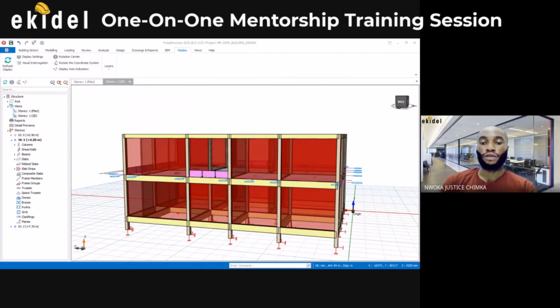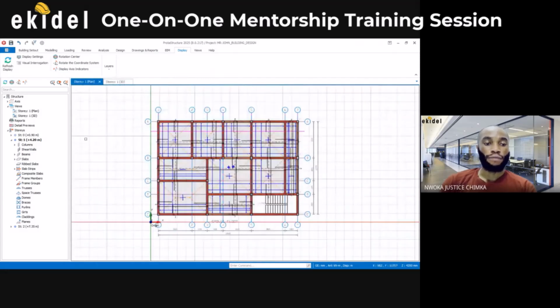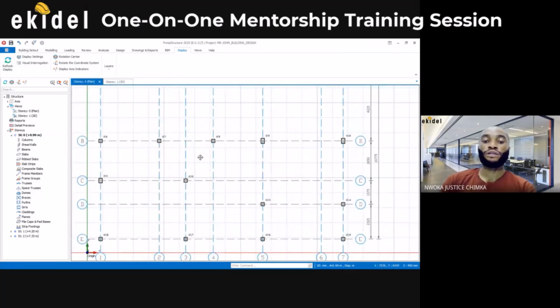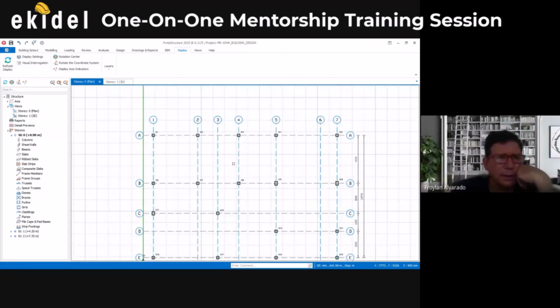I'll click on OK. Now I'll go back to story 1 and make story 0 active. Story 0 becomes the foundation level. So I'll make story 0 active, click on it, and then you see only our column points and all that. So let's do that again.